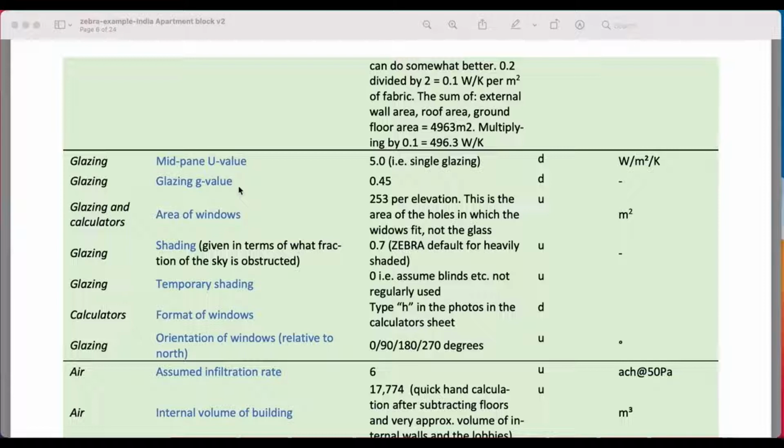Now, you've got somewhat less than that on a vertical surface, the sun will be at an angle. You've also got the fact that glazing will reflect some light. But it's pretty clear the number of watts per square meter is likely to be very large. And if you don't get that right, then the energy consumption of the building will go completely wrong. If you assume there's too much light getting into your building, maybe the cooling load will be much, much higher than it actually is in a hot part of the world. And if you're in a cold part of the world, if you think there's more light getting into the building than there is, you're going to predict a low energy use from the heating system, and it ends up being a very high energy use.